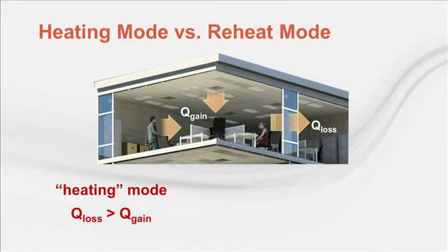suited for heat recovery. While these coils are often referred to as reheat coils, I think it is helpful to recognize that they have two functions. During cold weather, the heat lost through the building envelope and glass can exceed the heat gained inside from people, lights, and equipment. Under these conditions, the zone has a net heating load, so the air must be supplied at a temperature warmer than the desired zone set point.